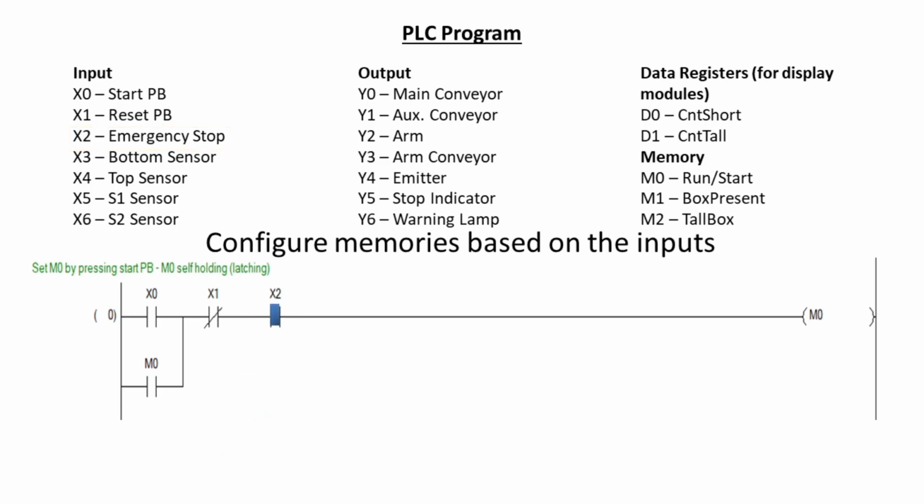A normally closed contact is utilized for the X1 pin. This indicates that the contact remains in its normally closed state until a 24-volt signal is applied to the X1 pin by pressing the Reset push button. Alright, now that we understand the contacts linked to X1 and X2 stay closed until the Reset push button is pressed or the emergency stop is activated, let's see what occurs when we press the Start push button.